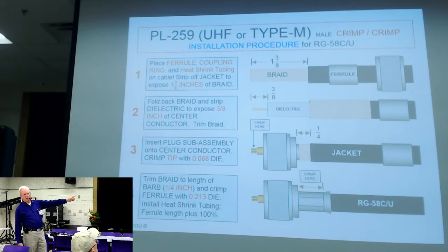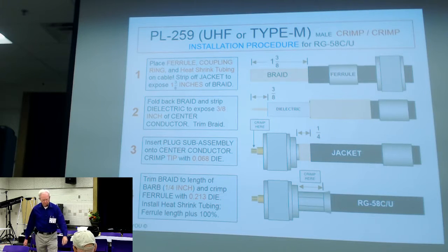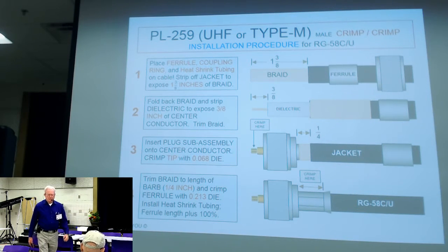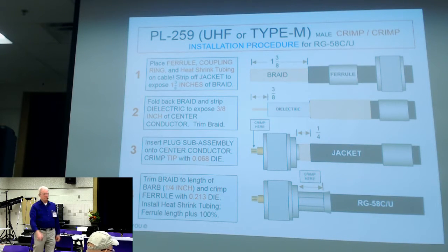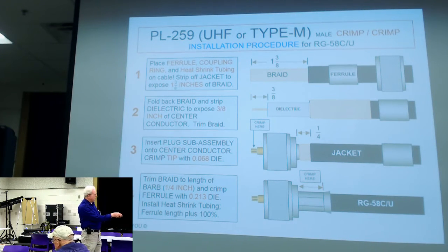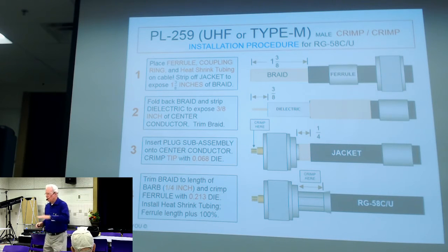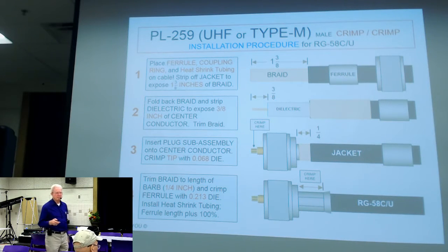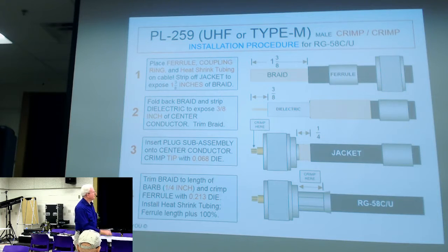I have the crimp and the solder. Let me pass around the crimp. There we go, Ray. There's the crimp. Now, the first thing you're going to see when I pass around the crimp is that I have a little ball of solder here. So I crimp the pin, but what I do, I cap it with silver solder. I put a nice little hemisphere of silver solder, and it looks so pretty. It's all in how it looks.